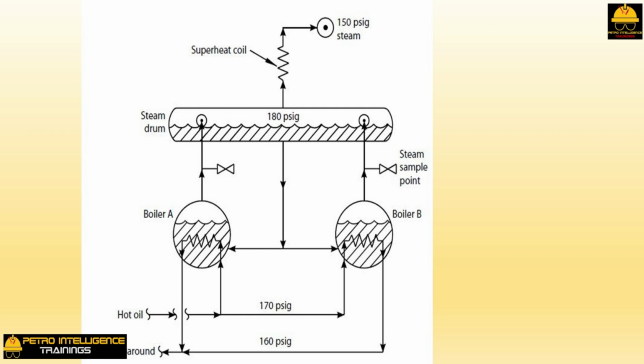However, when boiler A was hydrotested by the maintenance department, no leak was found. So, boiler A was returned to service. But, as the operators restored the flow of gas oil to boiler A, the indications of water intrusion into the fractionator returned. The operators, quite angry, again removed boiler A out of service and insisted that the maintenance department this time find and actually fix the tube leak in boiler A.